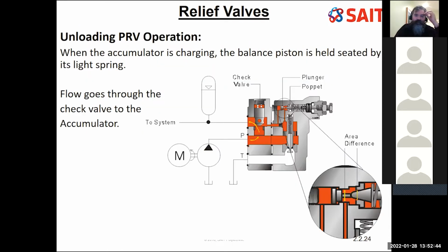And let's have a look at how this valve is often used with an accumulator. Remember back to MEC 205, I talked about an accumulator. It's like a balloon. If you blow a balloon up, I've stored air under pressure. It's the same with a hydraulic system. When we get to accumulators, you're going to see some of them are pretty much like a balloon. We act against a bladder and increase the volume of fluid stored under pressure, much like an electrical capacitor or even the battery in your phone.